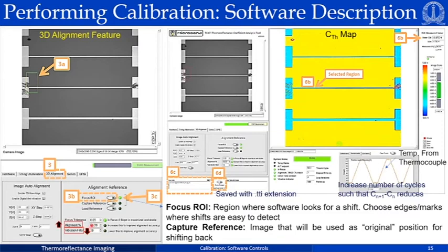There is another number called the vibration filter, which needs to be lowered to improve the alignment accuracy. So you have to increase the alignment percentage and lower the vibration filter number to improve alignment accuracy. However, one must note that if you keep these numbers too stringent, then the measurement would take a very long time. So you have to find an optimum number for the alignment percentage and filter number, where the alignment score is good as well as the measurement time is not too high. Okay, with these numbers set, we would then click on start measurement and the measurement would be carried out.